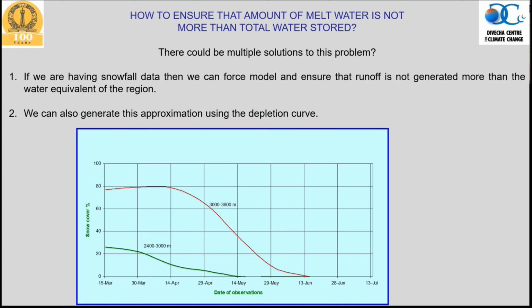That means we know the spatial distribution of glacier depth, and if we know the density, we can estimate the water equivalent. So if we know the water equivalent of snowpack by various means, either by field investigation or by other remote sensing techniques, particularly gamma ray, scintillometer or other meters, or some microwave techniques, you can know that.